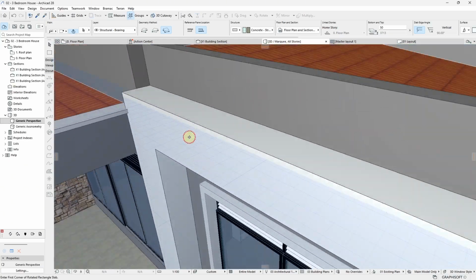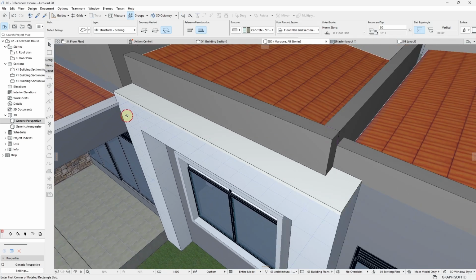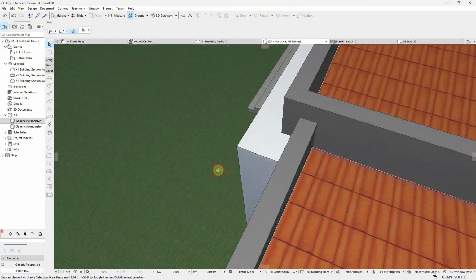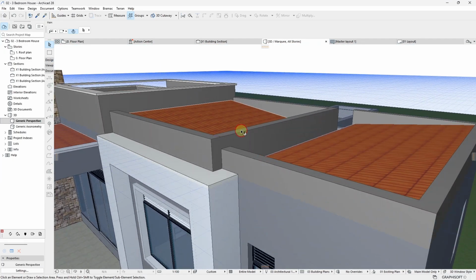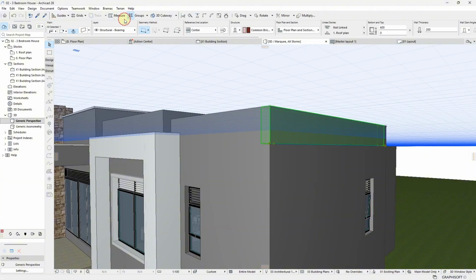Of course, this part up here can be built in brick. I think we all know that. If you have your iron bars, you can lay them across, lay bricks on top, and you slab it up. I think that's possible. So that's what I was saying: make sure it is as cheap as possible. So our roof will drain here. Even that roof will drain at this same point. And then I want to do a parapet here.